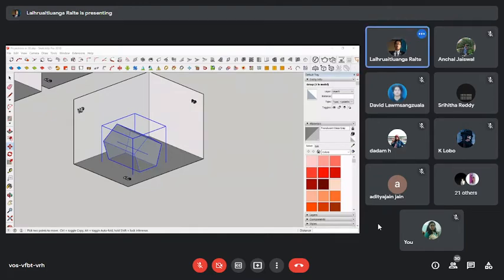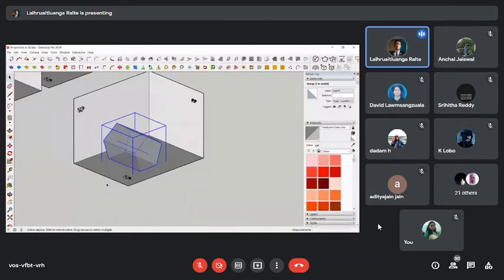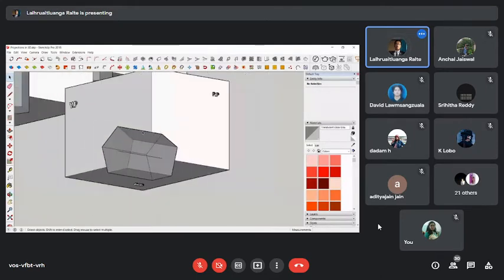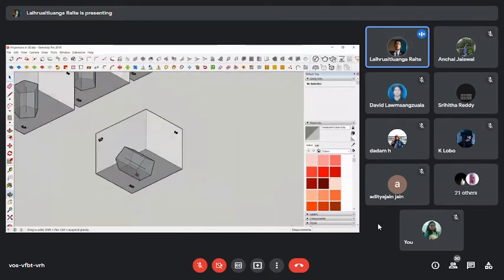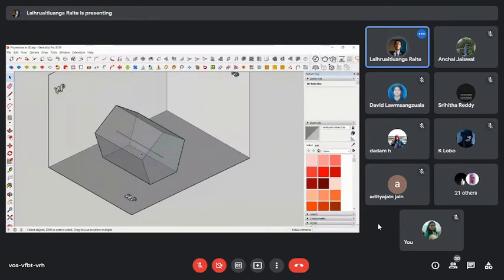All right. So now we have a pentagon. Oh, sorry, pentagonal prism. We have a pentagonal prism, and in this particular orientation, we have the axis. Now I hope you can see the axis. Now we have the axis perpendicular to the VP, right? When it is perpendicular to the VP, that axis is parallel to the HP, okay?